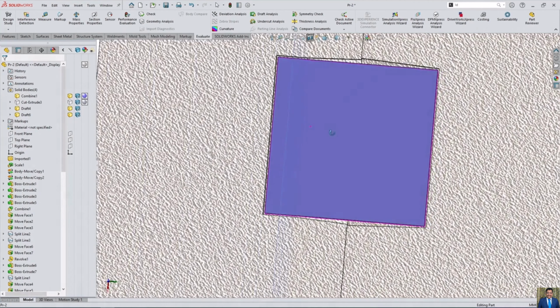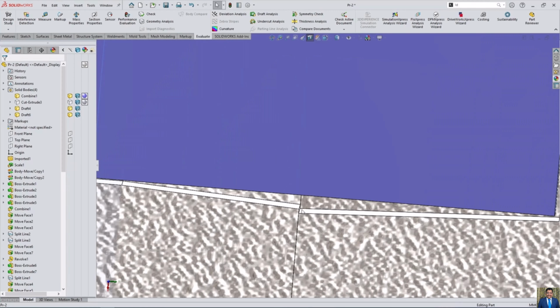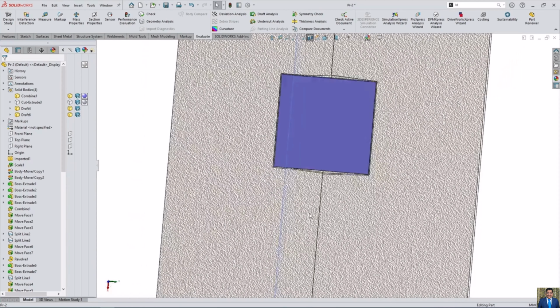Why we put the filter like that, and one side it should be a little deeper, because when you put the filter in this direction it should be stuck here, and when the mold closes, if the filter goes down, and when another mold comes, it touches and breaks the filter every time. It's better if you go like that on one side.